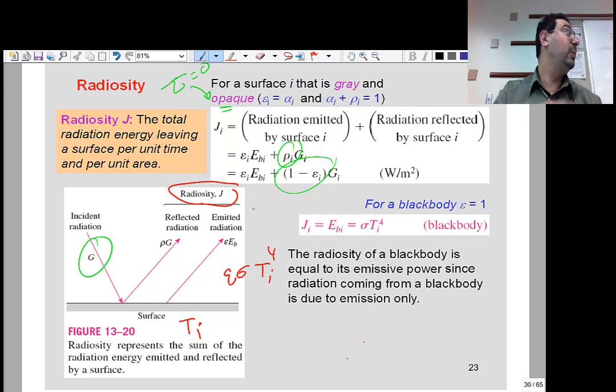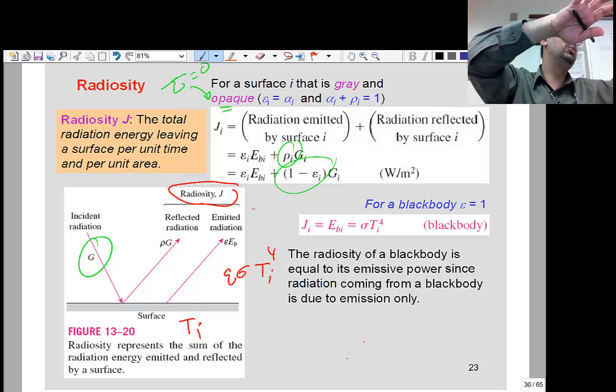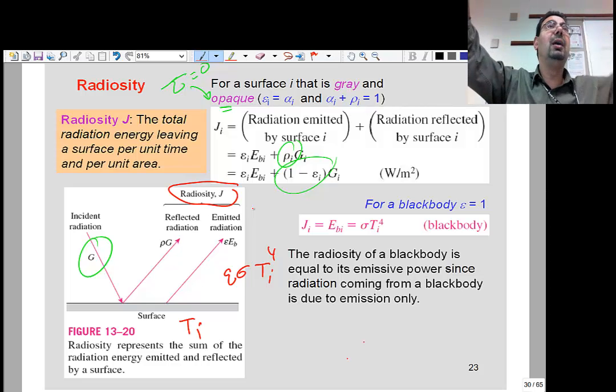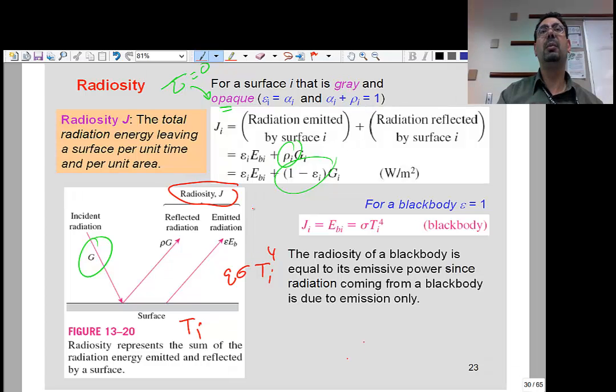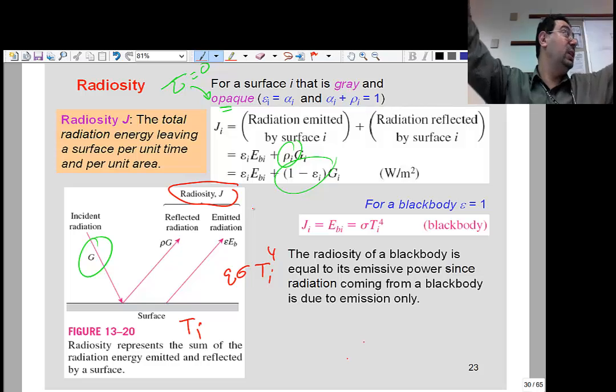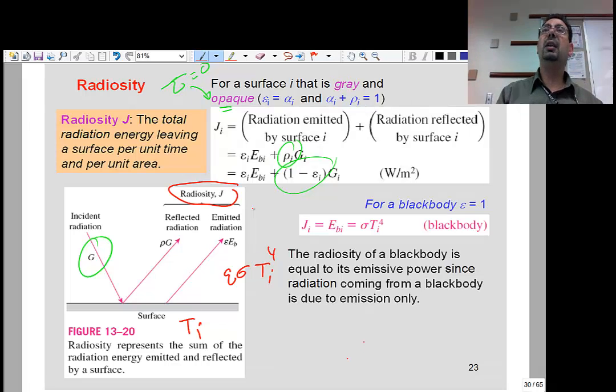We will turn this problem into also 2 things. It's not going to be T, but 2 things and the resistance between them. And the Q would basically be those 2 divided by the resistance between them. The 2 things that we had in conduction were T1 and T2 divided by the resistance. In radiation, it will actually be the radiosity.